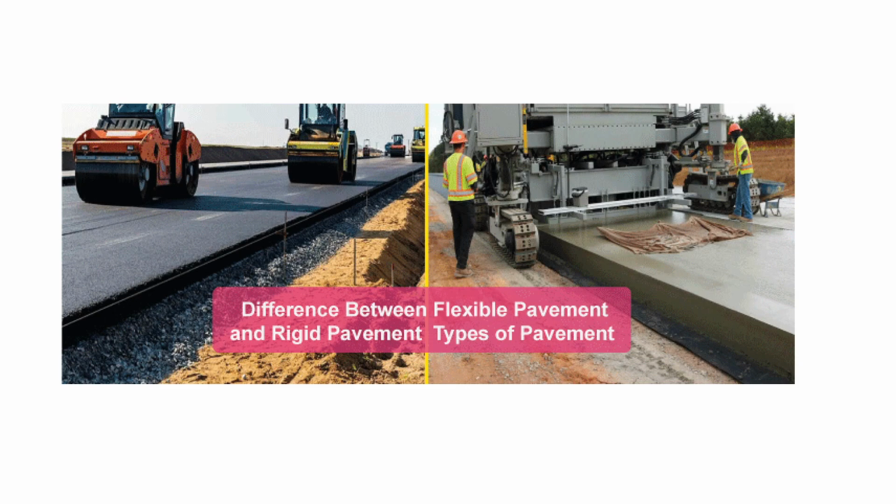After that there is a prime coat. Then there is a DBM, dense bituminous macadam. Then another layer comes, the tack coat. Then after that, the topmost layer is a BC, bituminous concrete, right?